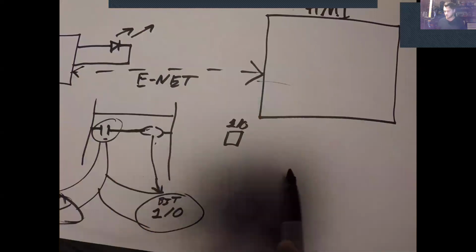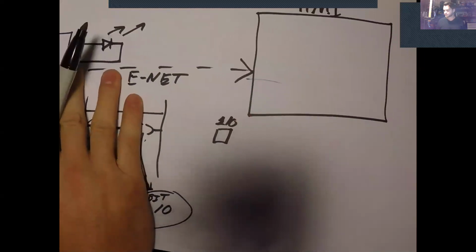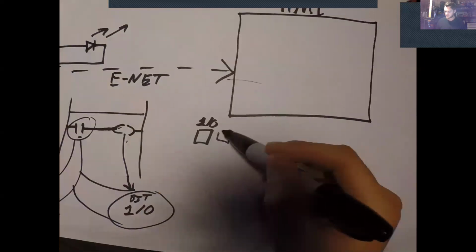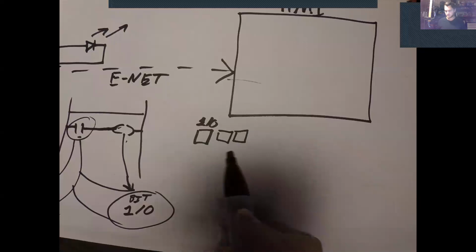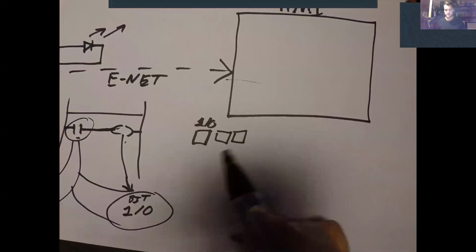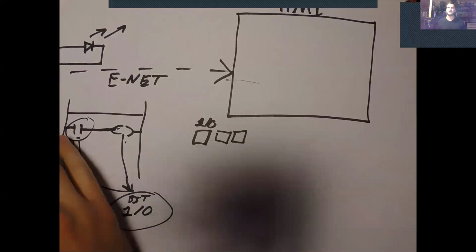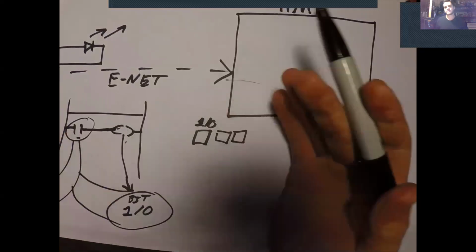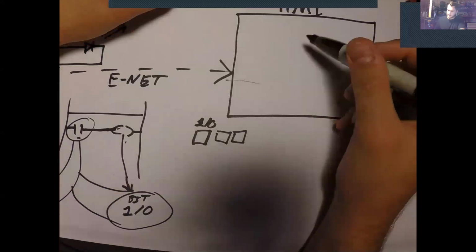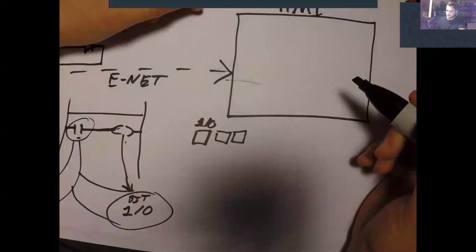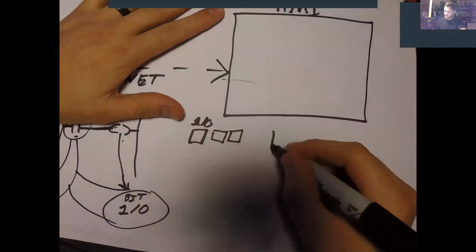The status of this memory is controlled by an external stimulus, right? And I'm just full of these blocks and I don't know what's writing in or out of these or what's reading them off. I just know what the status of those bits is, right? And so for the HMI to PLC communication, all you have to do is define tags.